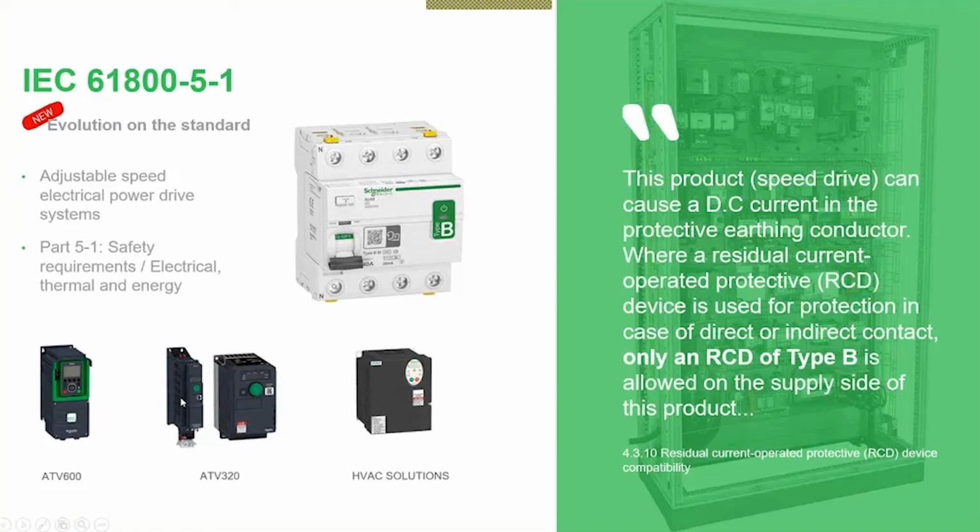Variable speed drives, it's well known that they are capable of producing earth leakage currents of various frequencies where a Type A RCD is not suitable for use. It's also now mentioned in the IEC standard 61800-5-1, which is specifically for the safety requirements for electrical and thermal energy when VSDs are in play.